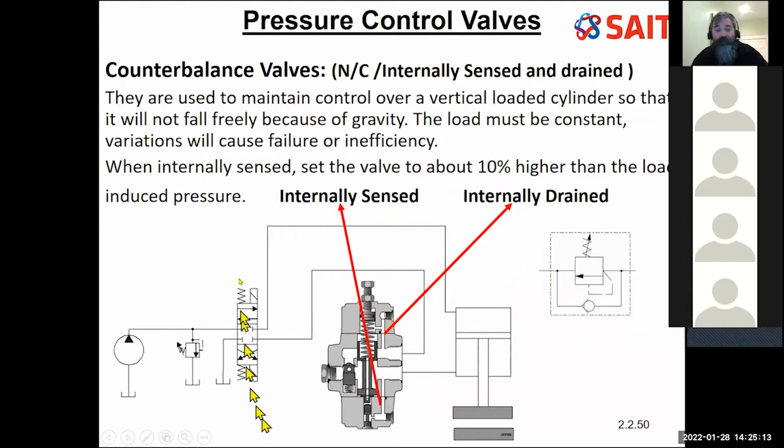So the same Vickers valve, set up in the same configuration as I had for my first valve, my reverse pressure valve. I can't remember what I called that valve. I'm going to set up this valve instead of over here to create back pressure near my point of work instead of for the whole system, just as this item here.